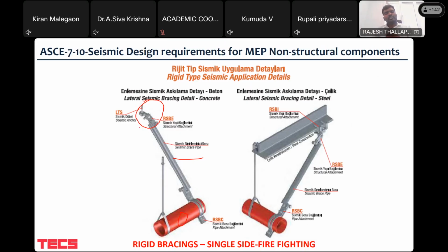Generally how we design is that we take the beam as a simply supported or a cantilever beam, apply a certain load, get the reaction forces and analyze whether the moment capacity is passing or the axial force is passing. So we do theoretical calculations and prove that yes, this is fit to use. But in fire, along with the theory, you also need to prove practically whether this seismic incident or this fire load, the fire effect, is going to be withstood by these particular elements or not.